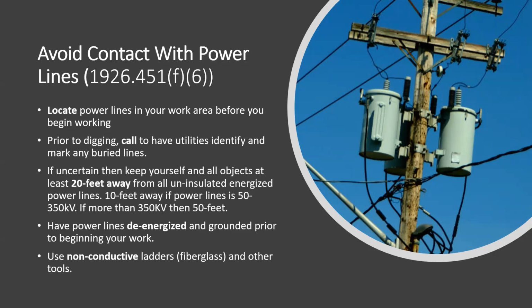Prior to digging, call the utilities. It may be possible that there are telecom lines going on. It might be possible that there are some electrical lines. Nowadays we also have fiber optics. So many types of utility lines are possible whenever you are going to perform digging or excavation.